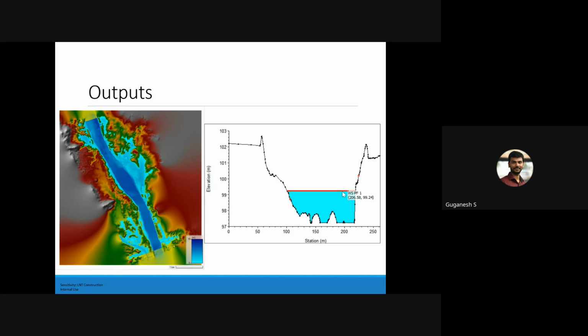For example, in our case, there are many pumping stations. A lift irrigation system includes many pumping stations located nearby the river. The work of the pumping station is to lift the water from the nearby river and uplift it for irrigation purposes. To protect the pumping station nearby the river from any flood, flood management is very crucial. This flood depth and extent is simulated for the pumping station, and subsequently, if it is safe, the pumping station can be kept at that elevation, or based on spatial information it can be moved to nearby locations where there is no flood inundation.